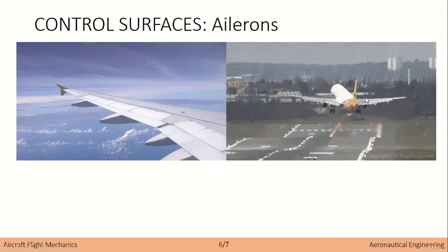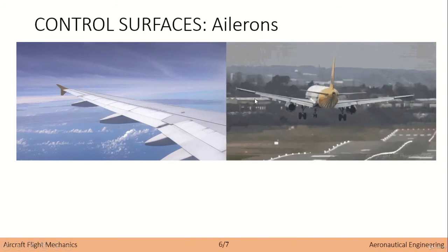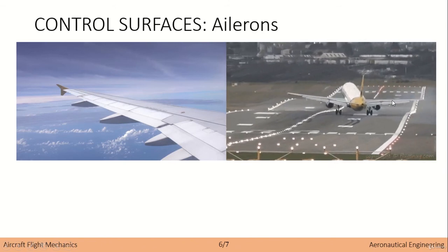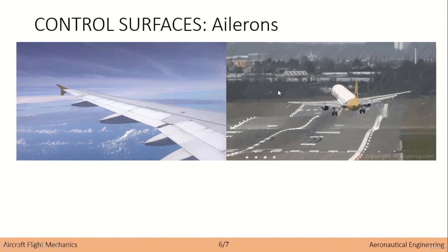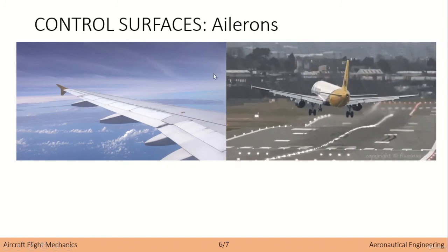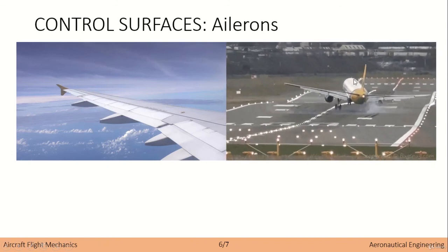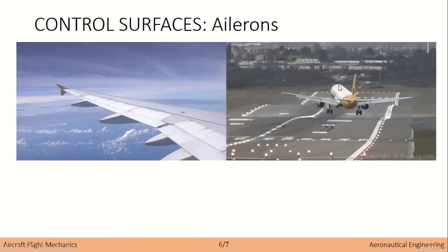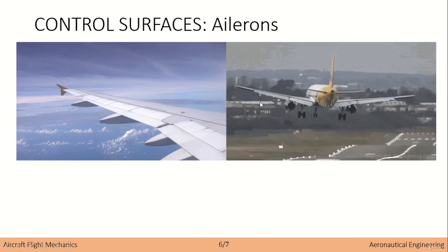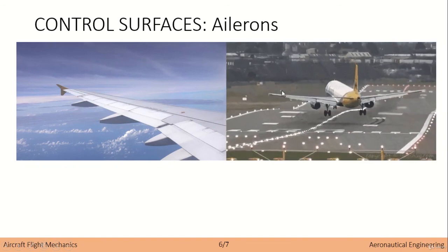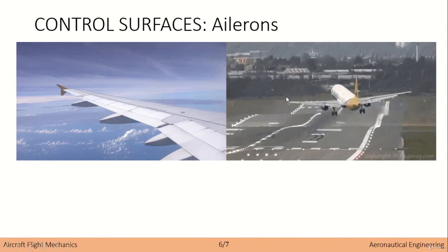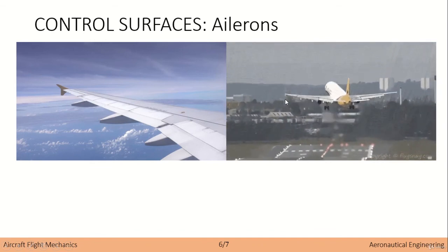Okay, so he actually uses the ailerons in order to stabilize the direction, the roll rotation, okay, of the aircraft when landing. You can see that in this case we had crosswinds, which are winds that come from a certain direction with respect to the vertical plane of the aircraft, so coming from this direction, and he has to stabilize it in some way or another using the ailerons. Okay, you can see here how the ailerons change, right, and how he tries to stabilize it, and the aircraft won't stabilize because there's a lot of crosswind in this case.